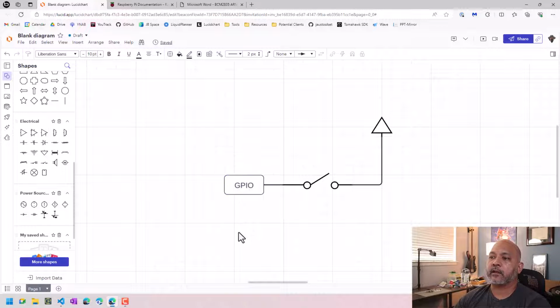So this means that when we read a value in the microcontroller, we don't know what we will get. It may say it's 5 volts, and we think there's a high logic. It may say that it's 0 volts, and we think it's a low logic, even though the switch is open. And what we're trying to say here with the switch open is that potentially the switch or the input signal is false.